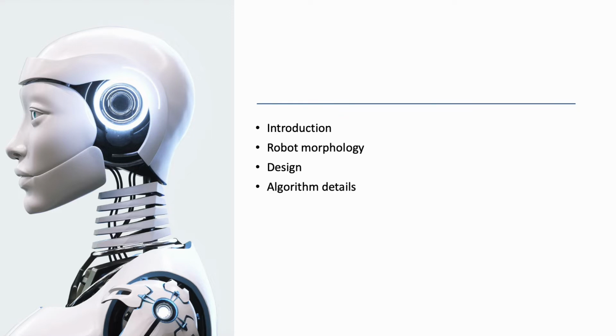And then the design follows a two-step procedure. Initially it creates a hardware template for the dynamics gradient, and then it sets the template parameters to customize the accelerator. For example, a target robot model is an industrial manipulator.